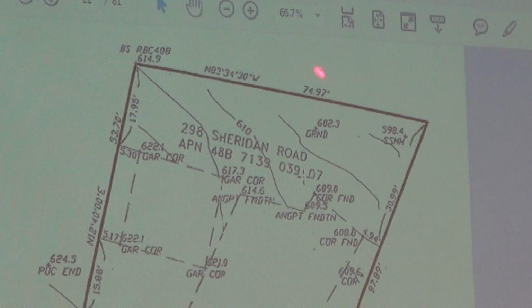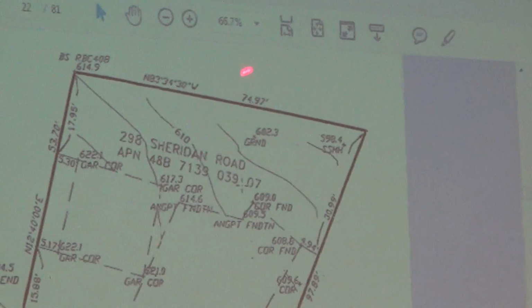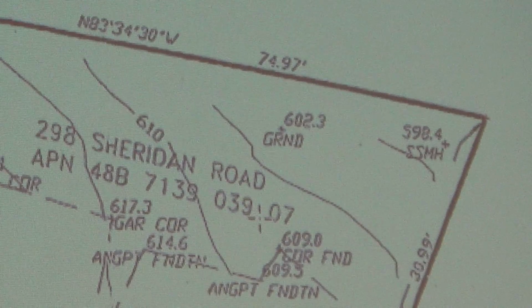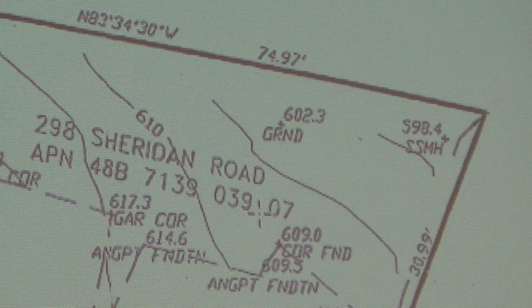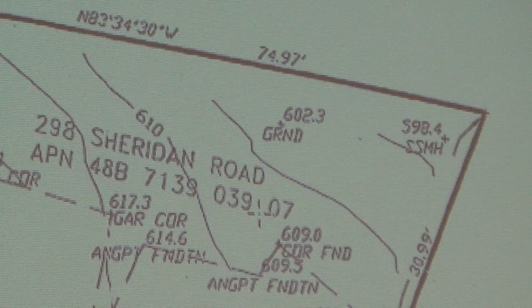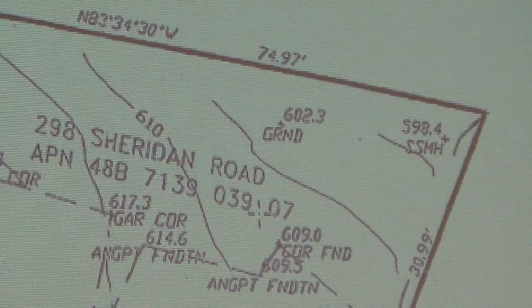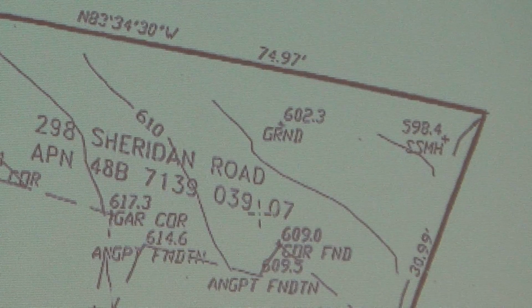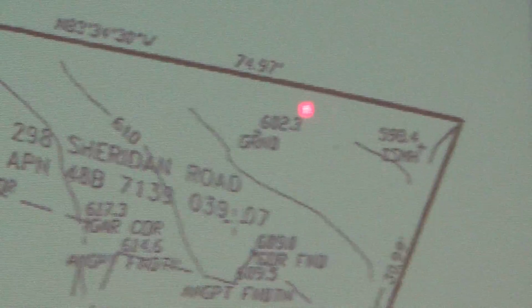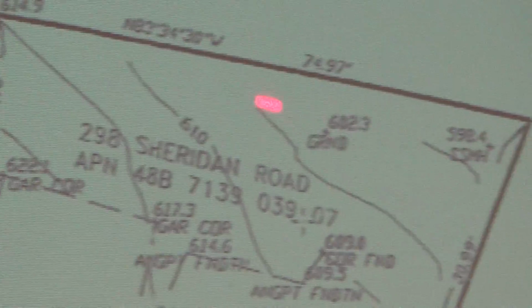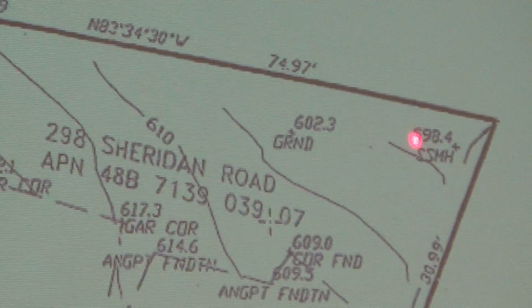Okay, so what is this now? Is this an angle? No, it's a distance, and it's one of 3. It's either a slope distance, a horizontal distance, or a vertical. What do you think it is? Horizontal distance. Yes. It's a horizontal distance. And let me explain why, but somebody called out vertical, so let's look at something here.